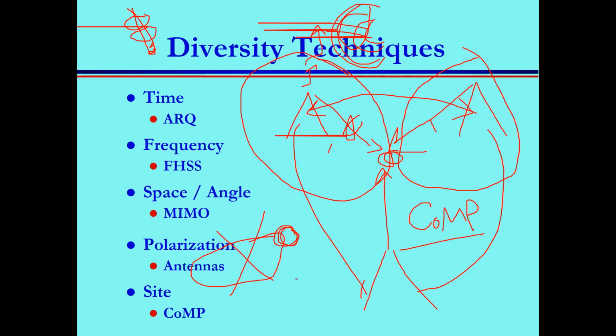We call this technology what? DIDO. Instead of MIMO, multiple input, multiple output, it is distributed input, distributed output. Why would you want to cancel this? Because of interference actually. You have other users who are located in this location. If you don't cancel your signal in that location, it will appear as interference to those users. Each user must get his own signal, not the other user's signal.